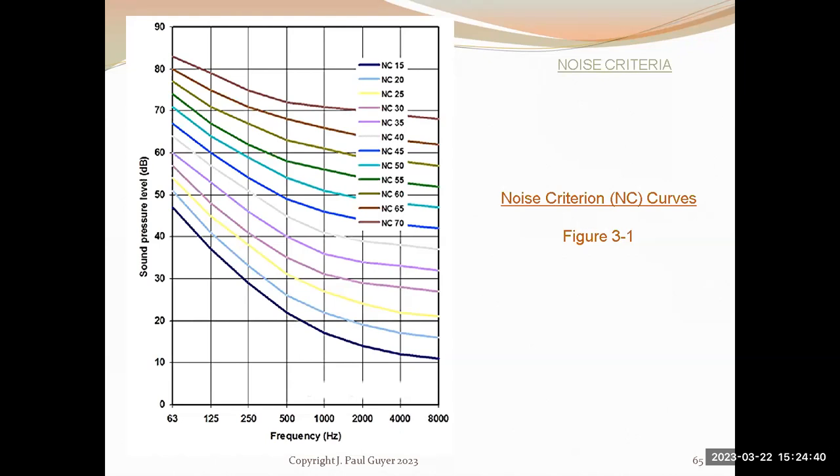And that's because these are the sound pressure levels that can usually be addressed through the design of the building, the walls, the ceiling, the floors, etc. You get above about 80 decibels, and that's where prolonged exposure of a human ear to that loud a noise, there's a high level of risk of permanent hearing damage.